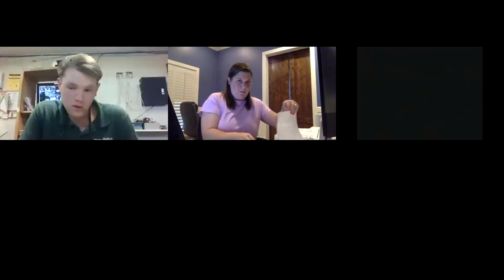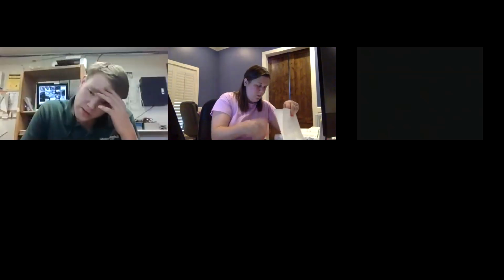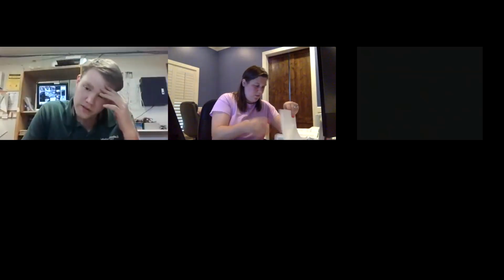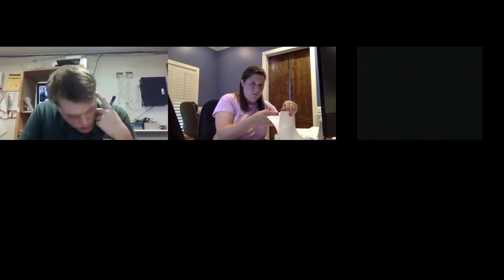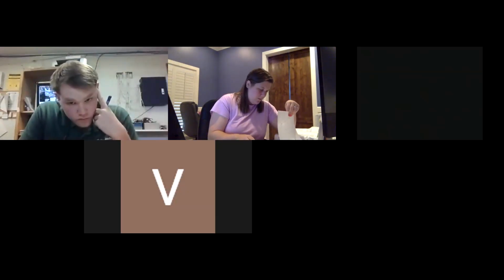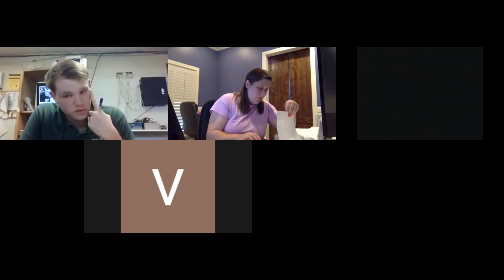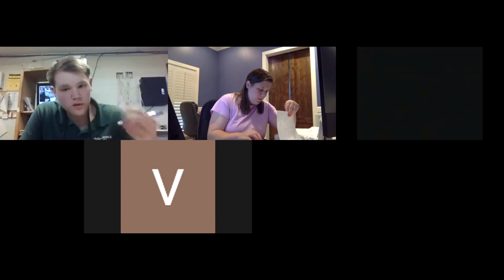As your VU. Hey, do you not have to compare like triangles because it's on a pin and a roller? So you just take the max shear as your VU? As your maximum VU. Yeah, okay. Just making sure. So the reaction force is the maximum VU? Yeah, in this case, because there's no dimension, right?